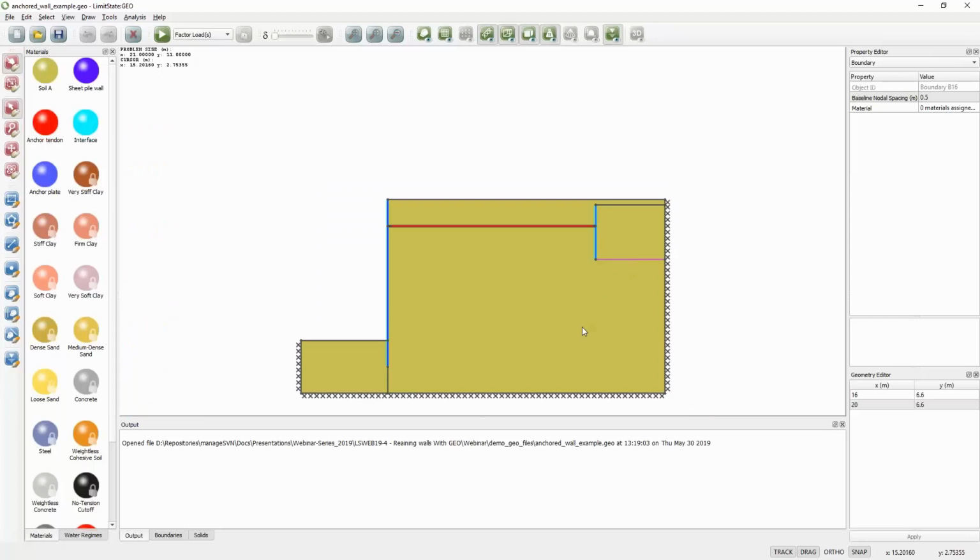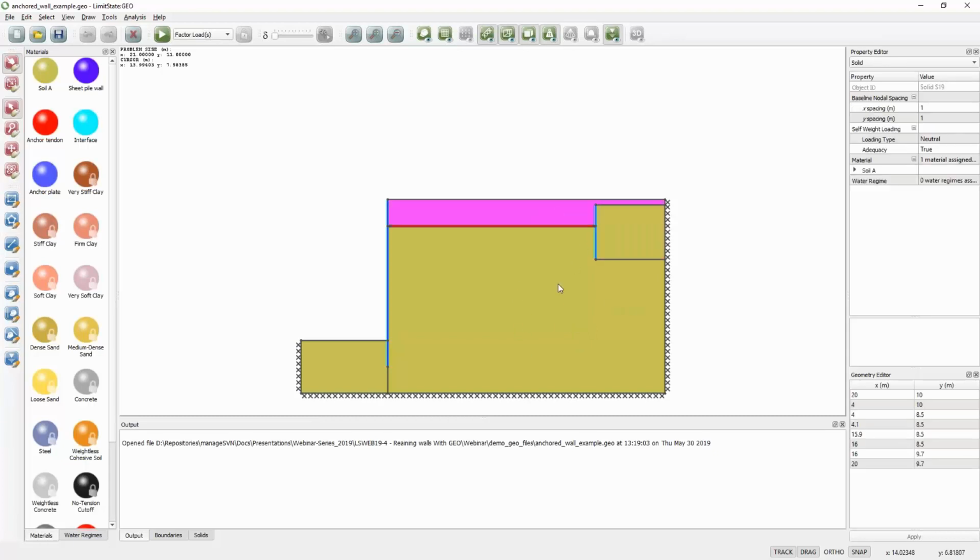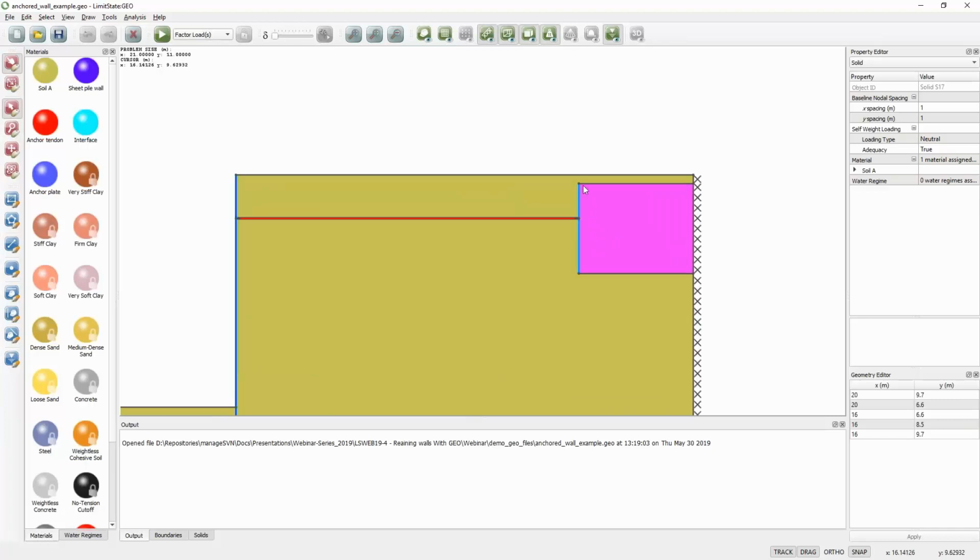So essentially the software, when we draw bodies in the software, they have to be in interconnecting blocks, so we can't just have a line which has got free ends. Basically we have to have distinct blocks of material for the software to be able to solve the problem, and we can't just have a free end of a single line. So these have to appear somewhere.